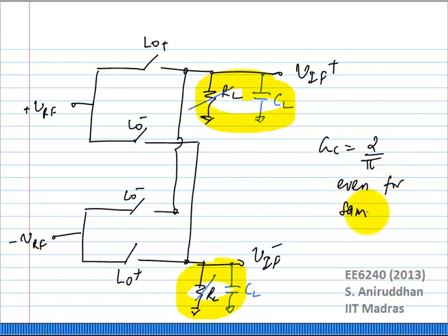So in other words, it's easier to see with the resistively loaded mixer. The original mixer we had a track and then a return to zero. Whereas if you take the output differentially, this has always only a track. Either you are tracking the positive side or the negative side of the input waveform. So you can think about it that way.